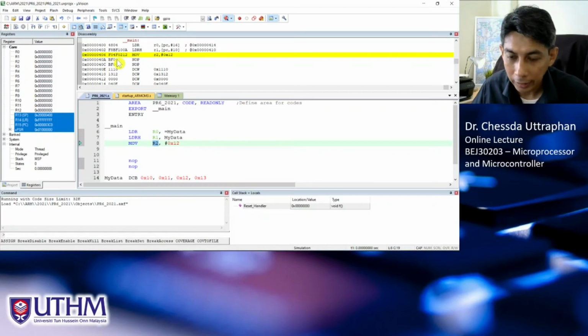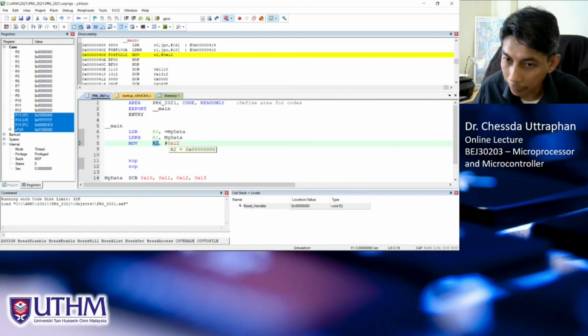So that is why in RISC microprocessors, particularly in the ARM microprocessor, because the size of the instruction is 32-bit already, you will not be able to have a 32-bit immediate value encoded into a 32-bit machine code, because that immediate value plus the information, for example, the code for the move, right?